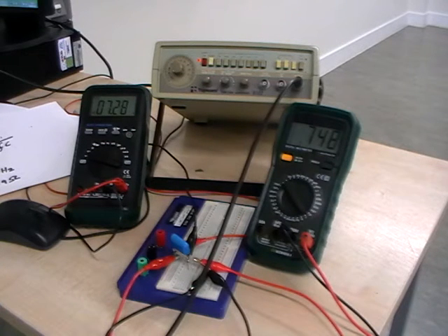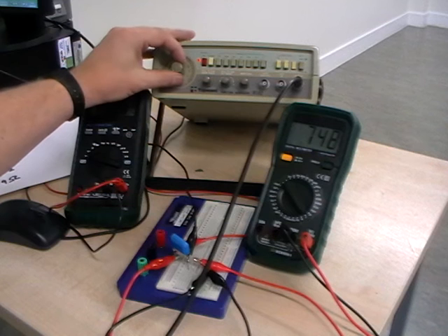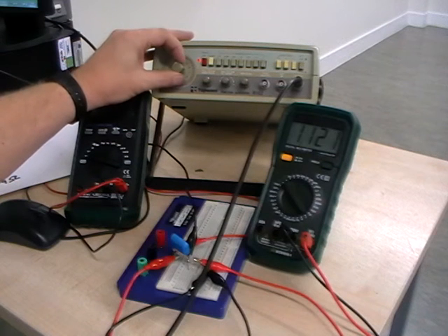Yeah. So can you see what's happening here with our capacitor? Yeah? It's responding to frequency. Frequency goes up, resistance goes down. That's what we have established here so far, using just basic concepts of Ohm's law. Okay, shall we go a little bit higher? Let's double it up, go to 200 hertz, see what it does.